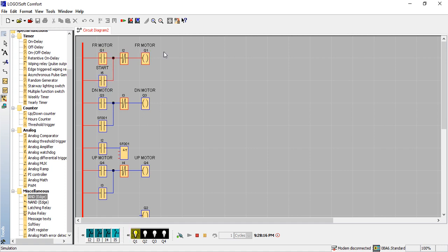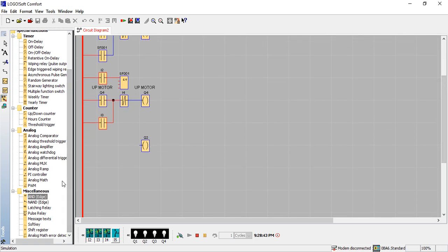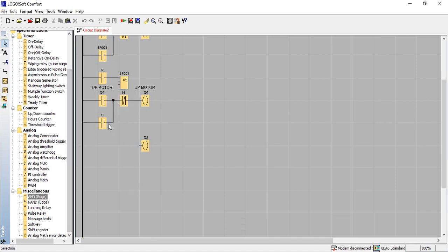I5, motor goes forward, it reaches I2, it stops at I2. Keep that in mind, and it goes down. Look at the signal that was going to I2. It's no longer there, but the motor managed to go down. Now we want the motor to go where? To go up until I4. And when it reaches I4, it needs to activate the backward motion. Very critical.